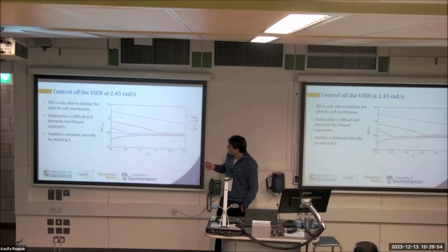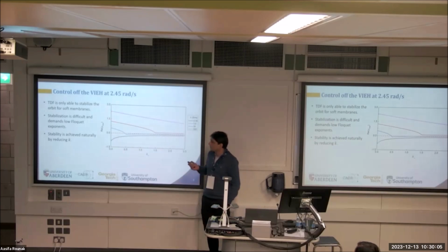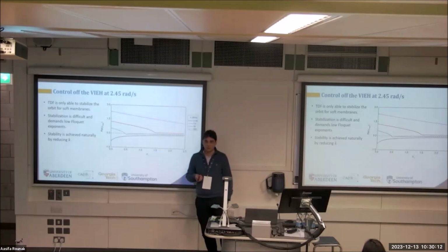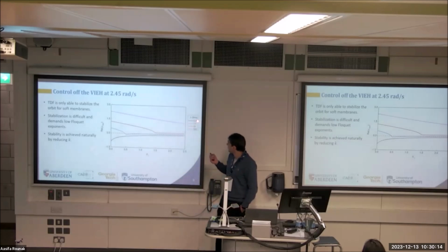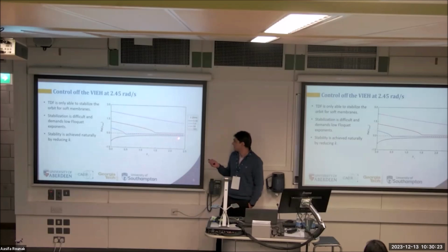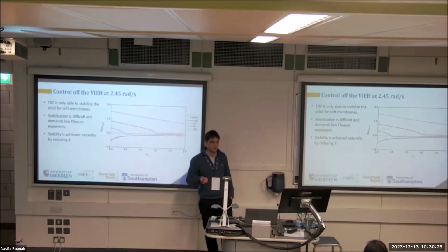you see that by changing our stiffness, we basically reduce the initial maximum real value of the Floquet exponents, indicating that we are reducing the instability of the orbit, to the point that if we lower our stiffness a lot, as in the case of 0.56, we basically destroy that attractor that we see, and it's already a stable solution of the system.